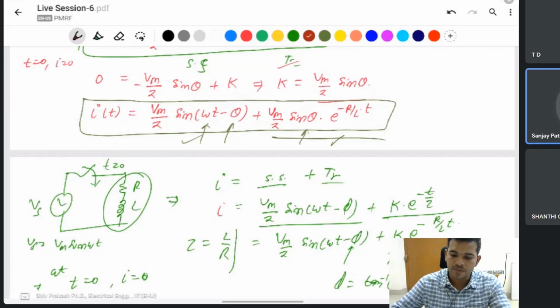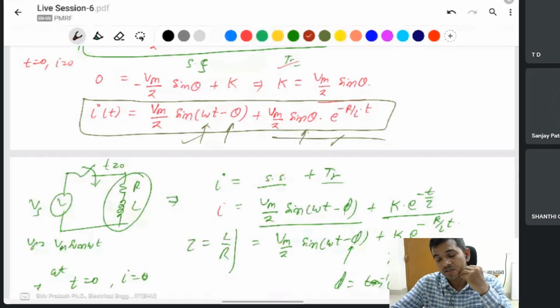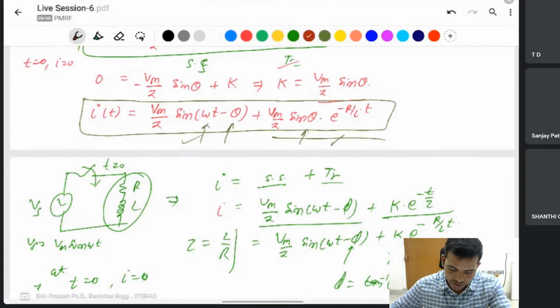You have to synchronize with the zero crossing. You know about circuit breakers or switching in a power system; electronic switches and electronic relays are present to prevent this at the time of switching, and for transformer switching also.